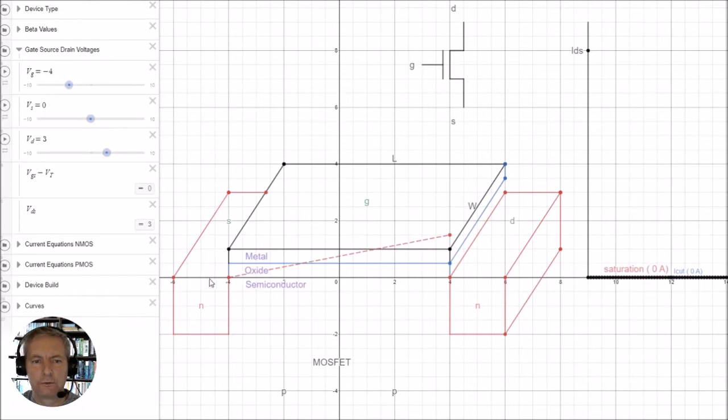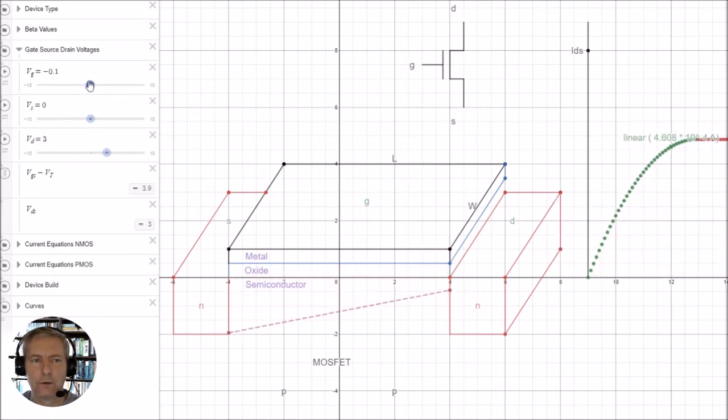So at -4 volts here, we can see that the device now is turned off. So to turn this device off, the gate voltage would have to drop all the way down to -4 volts. So we can see here that this device would in effect be normally sitting on at 0 volts.